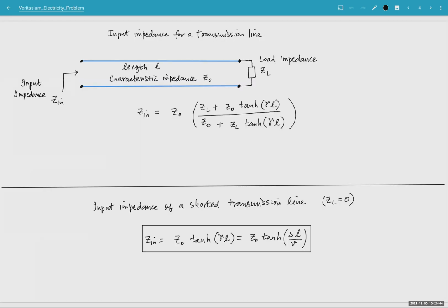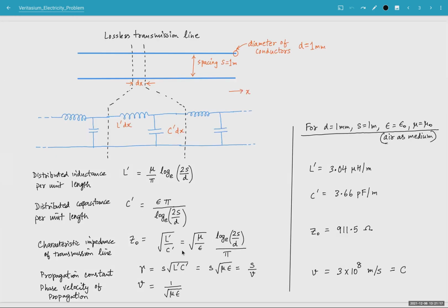Now, some other theory of transmission lines. If a transmission line is terminated by some load impedance Z sub L, then on the other side, the input impedance between these 2 points is given by this formula. And this is not necessarily a steady state impedance. The gamma, if you remember, is the propagation constant, going back 1 or 2 pages here. Gamma has this complex frequency parameter.